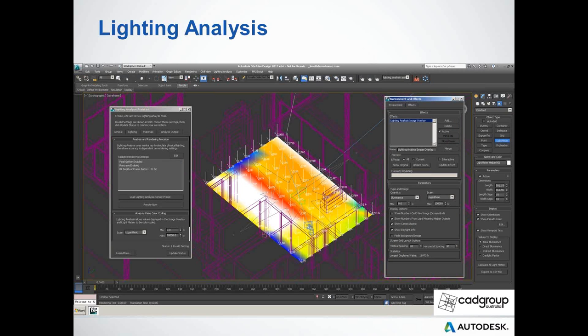So within Max you have a lighting analysis assistant that allows you to quickly create these light recording environments, and you can actually use this information to work out whether your internal space is receiving the amount of lighting that it needs to make it functional. So this is just another tool within 3ds Max Design which you can use within your workflows. And of course with this data you can actually export it out as a CSV file.